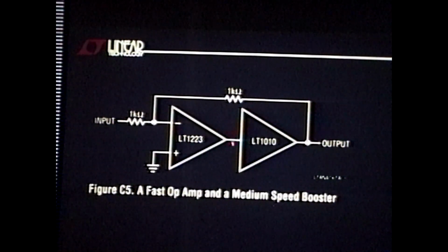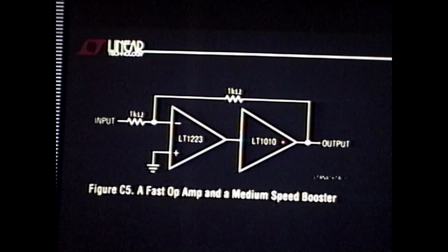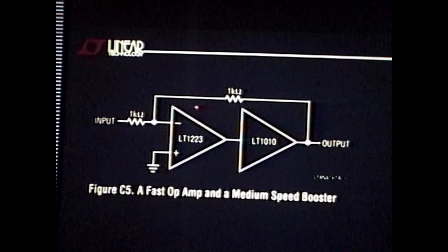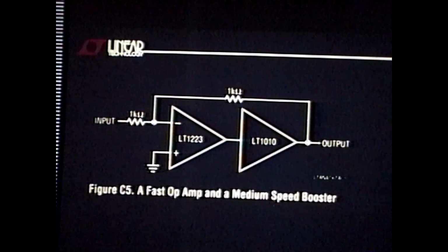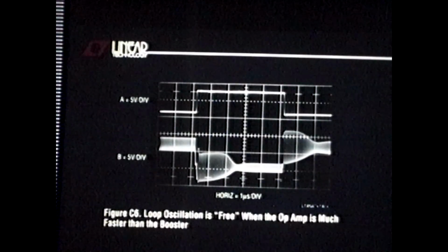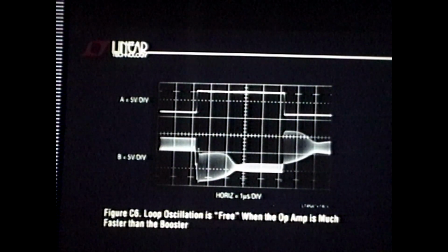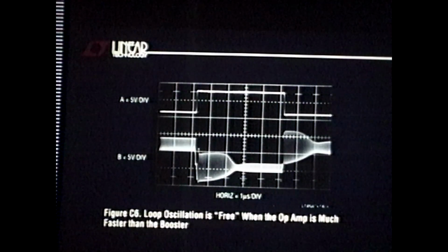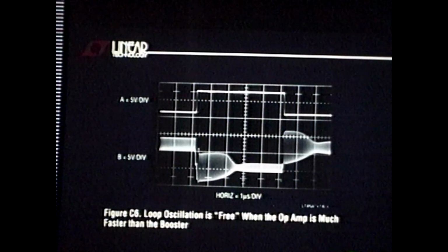So movement here is significantly phase delayed from getting around the loop relative to 100 megahertz of bandwidth available here. Put the same pulse in, it screams. The other thing you'll notice is, look at the frequency. That's the first question to ask. Look at the frequency of the screaming.